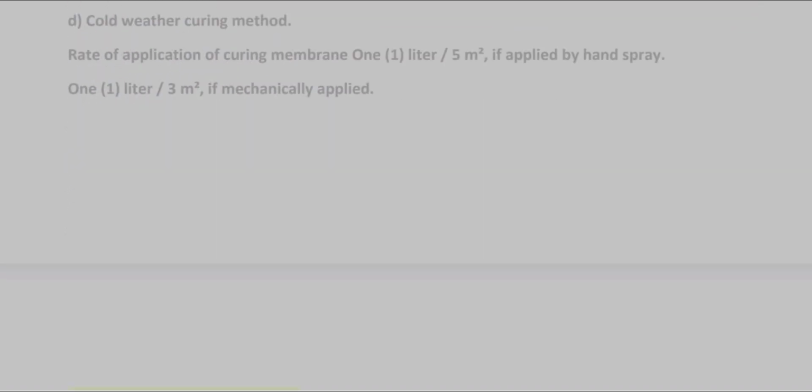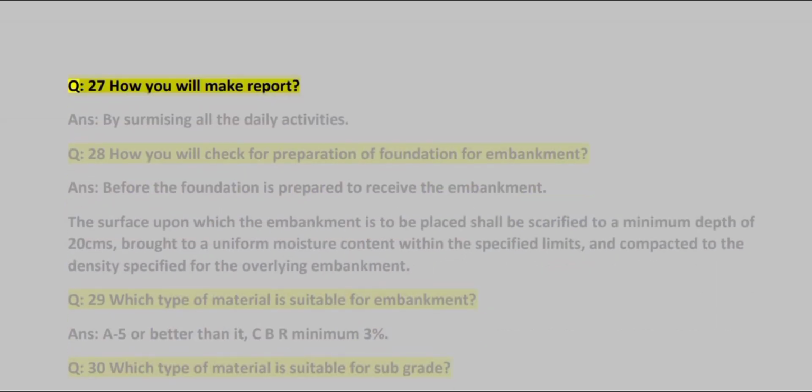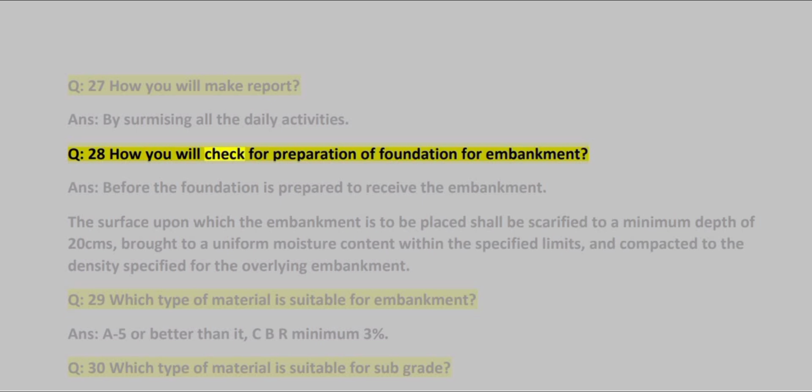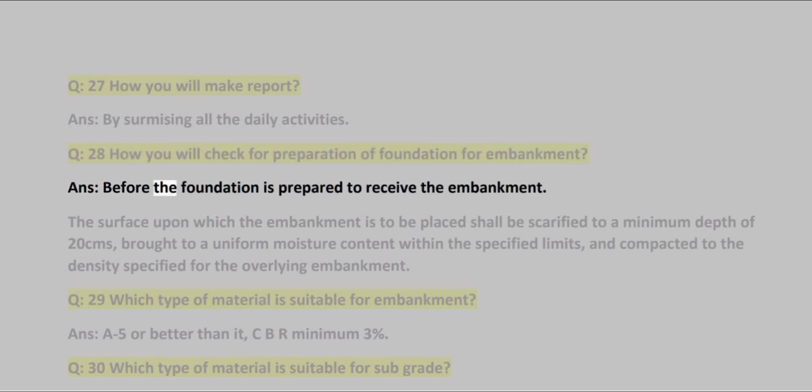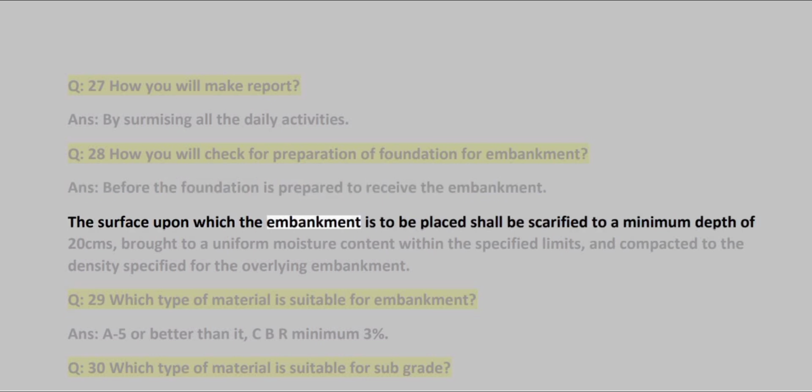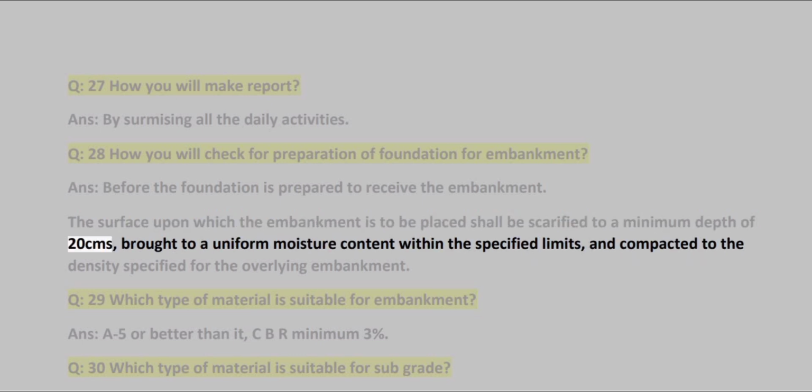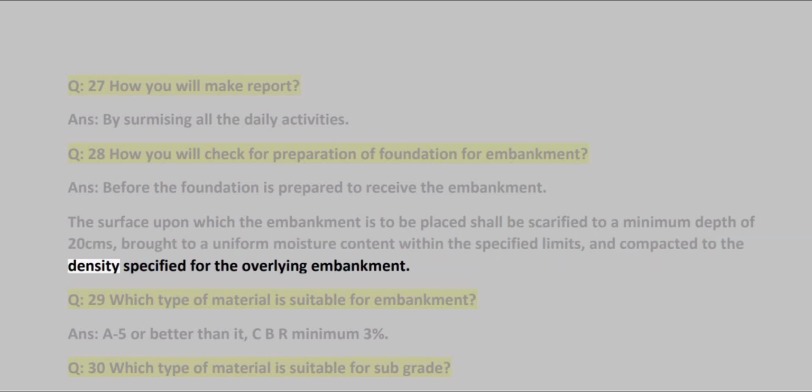Q27 How will you make a report? ANS: By summarizing all the daily activities. Q28 How will you check the preparation of foundation for embankment? ANS: Before the foundation is prepared to receive the embankment, the surface upon which the embankment is to be placed shall be scarified to a minimum depth of 20 cm, brought to a uniform moisture content within the specified limits, and compacted to the density specified for the overlying embankment.